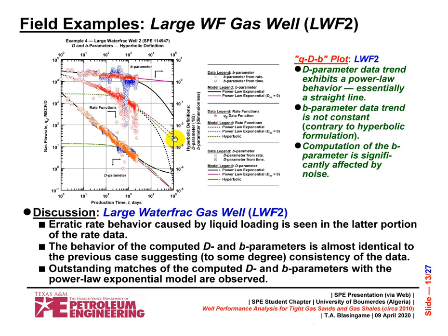The extrapolations are all reasonable. There is no deviation from this particular trend, which is the master trend. They all appear to have nice straight lines and no serious issues. There's no evidence of this curving out. There's no evidence of a D infinity being required. So this is very long-term transient flow.